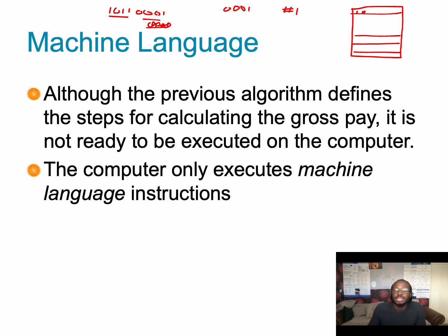So that's the operand. It's just to say it's a literal number. But the opcode is an instruction. So we decide when it sees 0101 or 1011, it means to load whatever is on the lower byte into memory. So even though this is 101100001, the processor will interpret it as load a literal number 1 into a certain memory location.